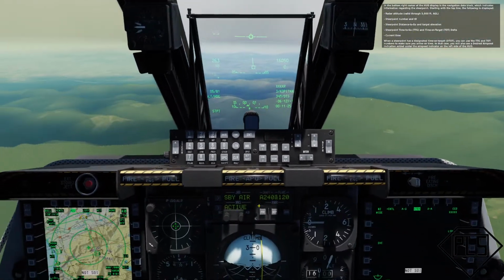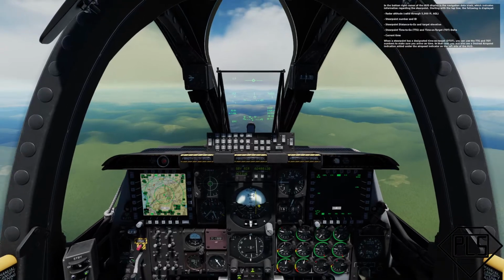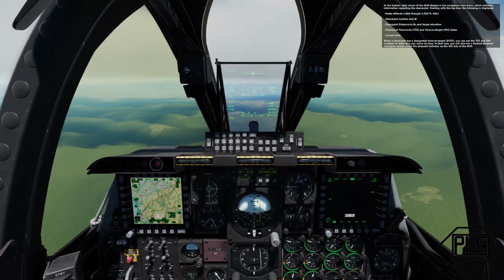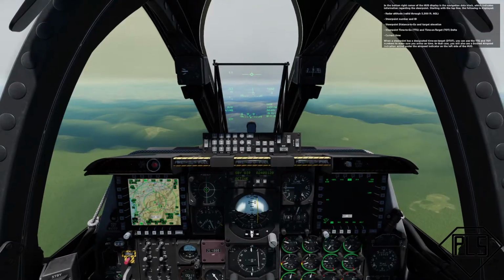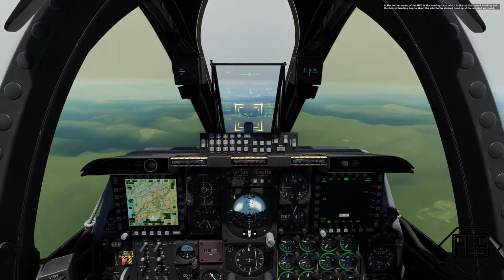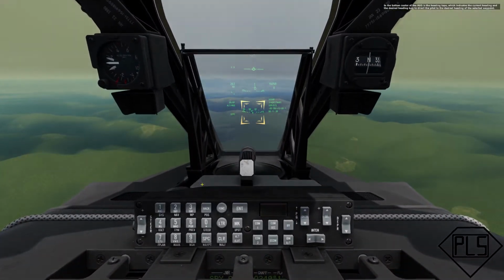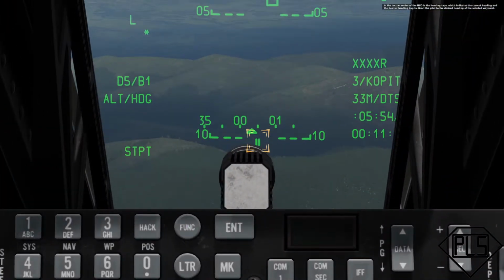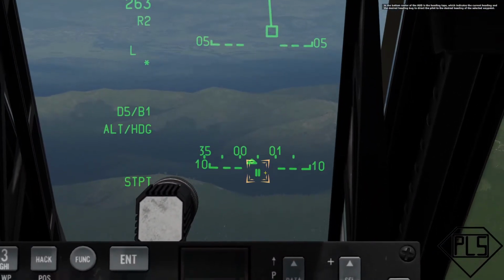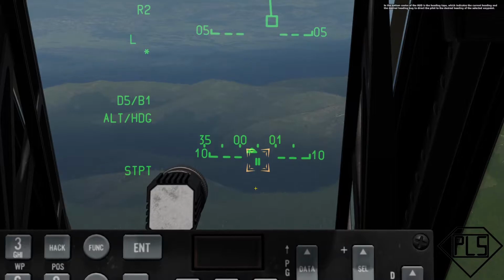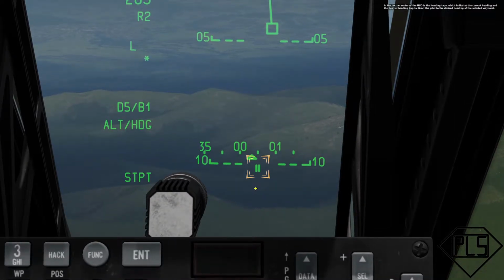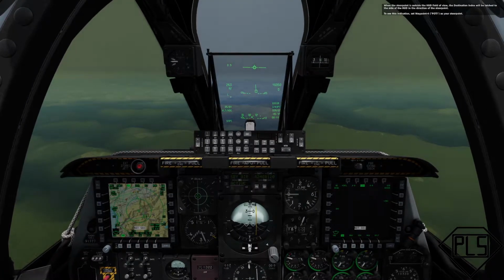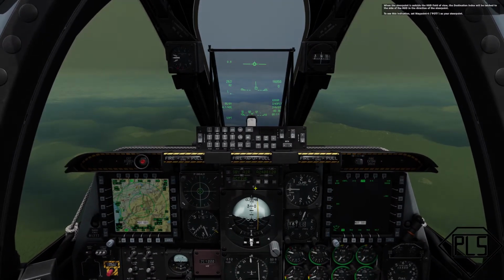In that case, you will also see a desired airspeed indication added under the airspeed indicator on the left side of the HUD. In the bottom center of the HUD is the heading tape, which indicates the current heading and desired heading bug to direct the pilot to the desired heading of the selected waypoint. When the steer point is outside the HUD field of view, the destination index will be latched to the side of the HUD in the direction of the steer point.